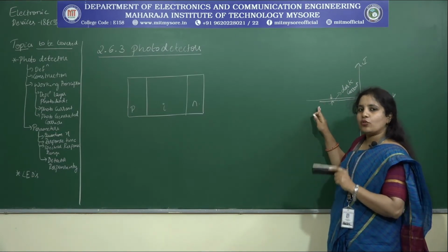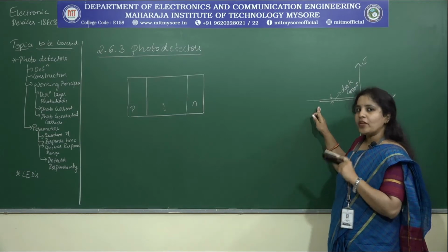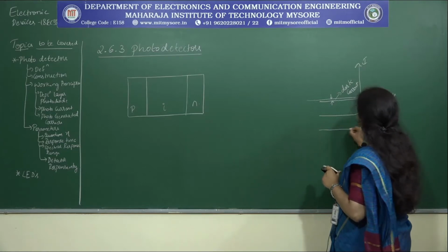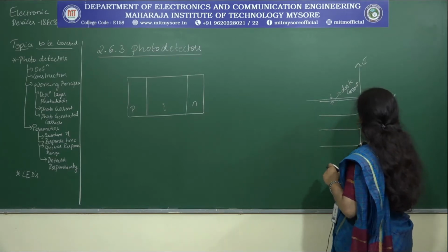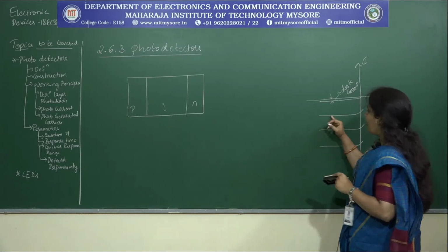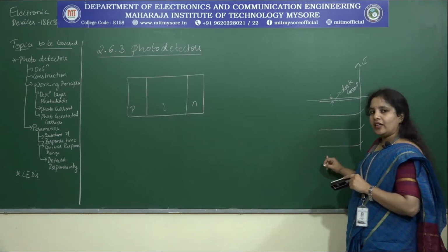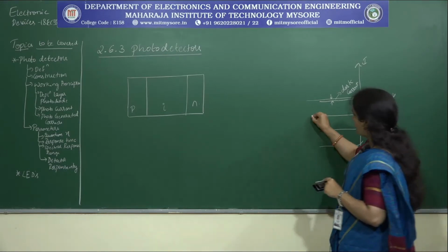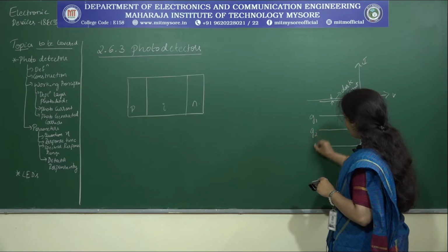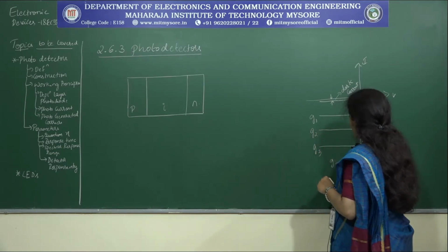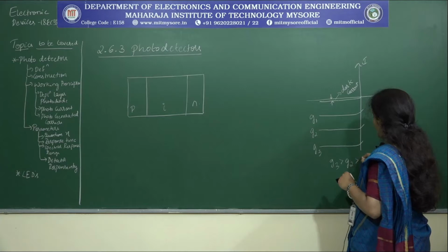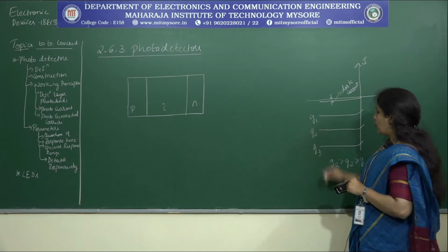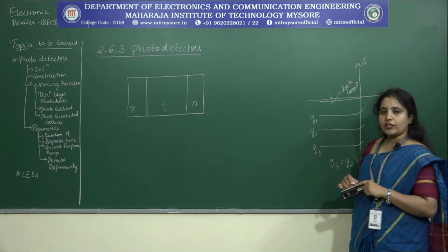Now, as I make the light rays fall on the device, what will happen as the intensity of the light increases? The generation of the charge carriers, EHP pairs, increases, and as a result, the amount of reverse current that I can find in the device also increases in magnitude. Yeah, so if the generation rates I refer to as G1, G2, G3, as I increase the generation rate, that is by providing more light energy falling on the PN device, then the reverse current also increases.